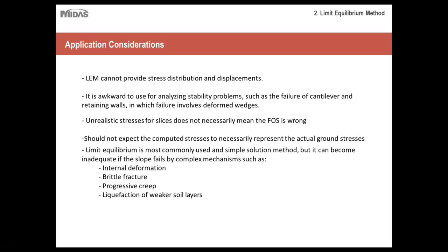But the main concept to grasp about the limit equilibrium method is that it's best suited for smaller scale, or not necessarily smaller scale, but simpler projects that don't require complex failure mechanisms to be taken into account, as well as displacements or large support structures. So if you have projects that are more straightforward, where you just need a factor of safety, and it's very simple as far as the materials that are involved, then the limit equilibrium method would be your most effective choice.